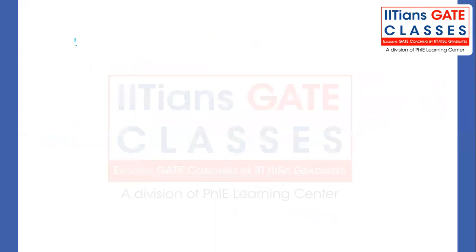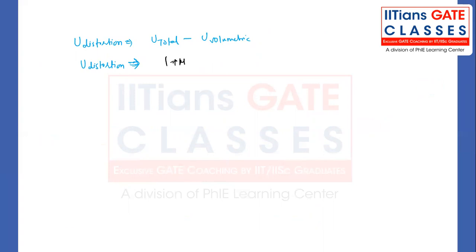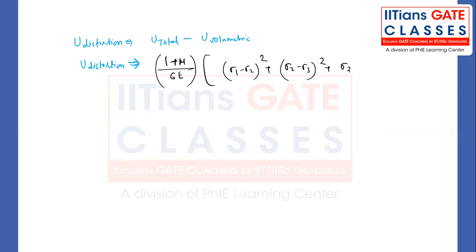So the formula of distortion energy is total strain energy minus volumetric strain energy. You can do that as homework. I will write the distortion energy formula directly, something like this: 1 plus mu divided by 6E, into sigma 1 minus sigma 2 whole square, plus sigma 2 minus sigma 3 whole square, plus sigma 3 minus sigma 1 whole square. This will be the value, right, my dear friend?